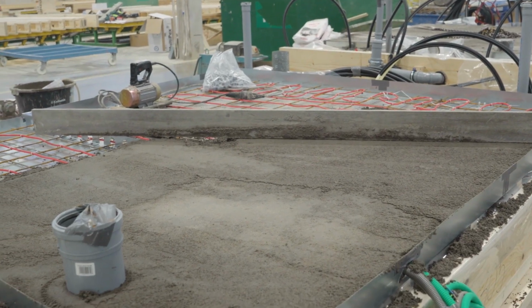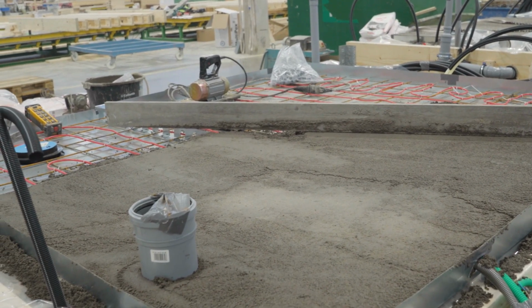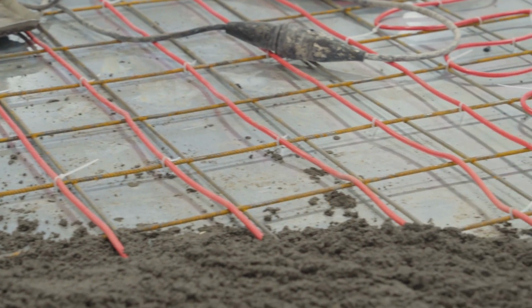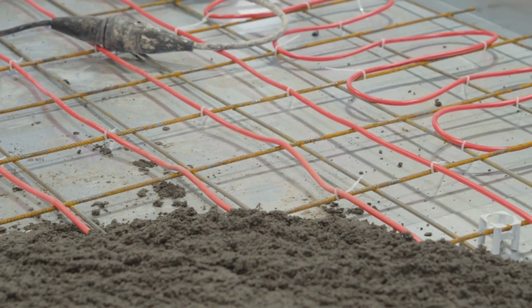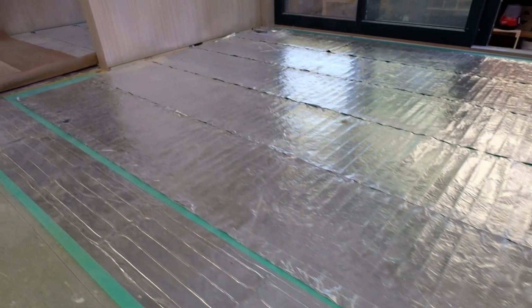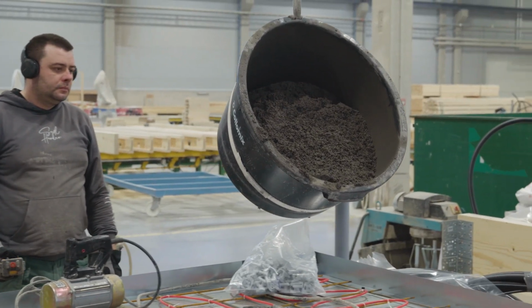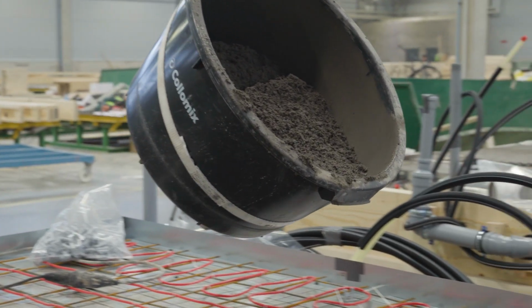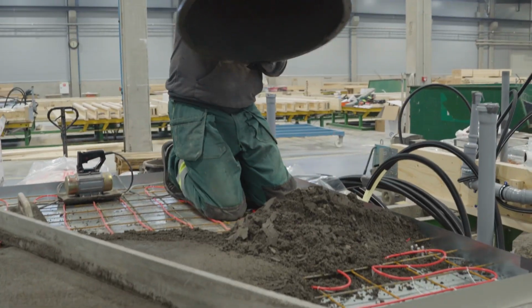If the bathroom has electric underfloor heating, then the heating cable is generally installed either in the concrete base plate or in the base of the ceramic tile in the mixture layer. When laying the heating cable, it is always necessary to take into account the location of the floor drain. The electrical wiring must be kept at a specified distance from the drain.